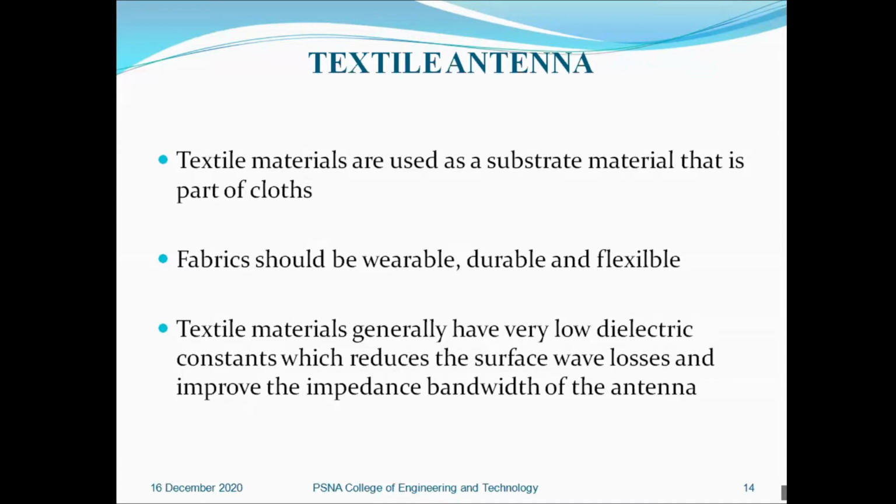Whatever material we have chosen, we can calculate the dielectric constant epsilon r. Or known materials with a known dielectric constant are available in the market that we can purchase as a substrate material for textile, which will reduce the surface wave losses and improve the impedance bandwidth of the antenna.